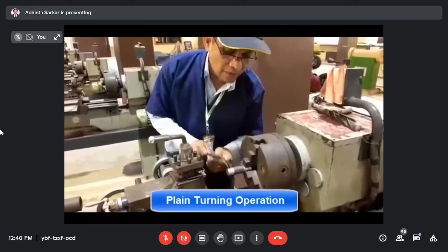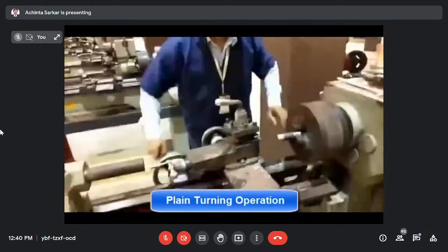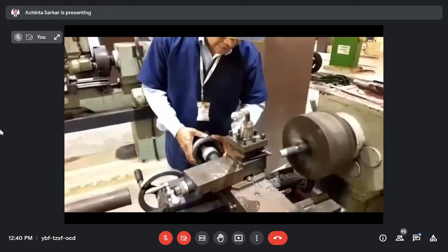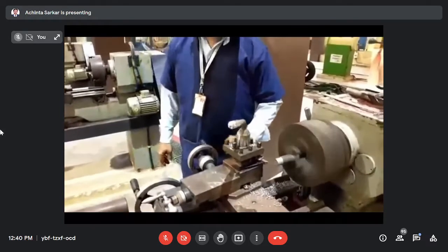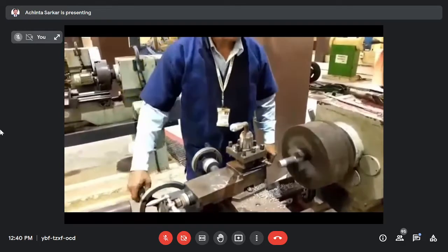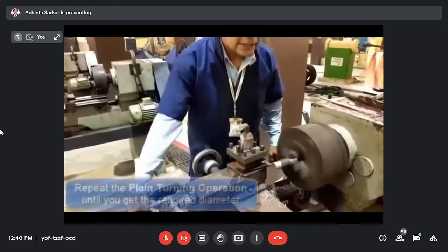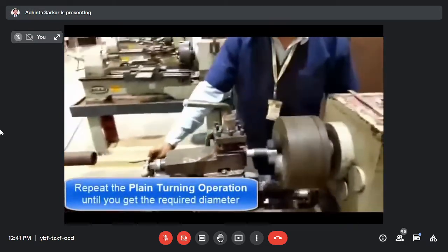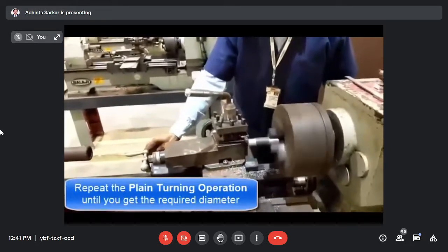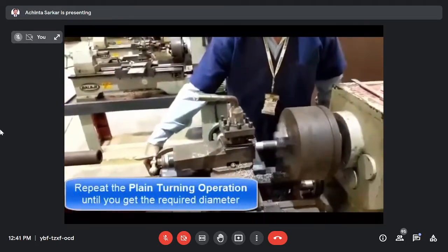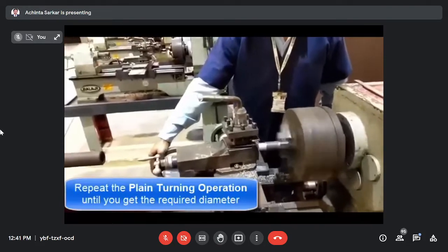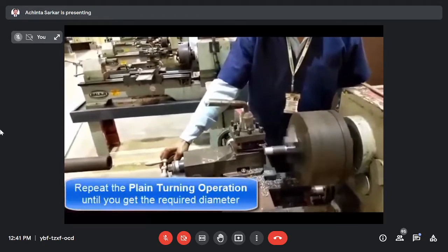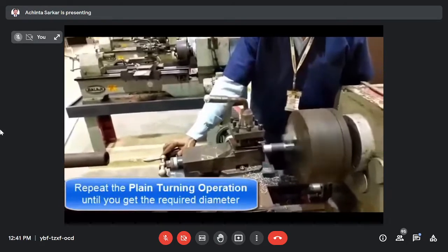No. 1 mm depth. Again here apply 10 divisions. 1 division is 0.02 distance. Then apply a fine cut to get the exact dimensions, slowly rotating the carriage wheel, and the feed rate is very less, and getting smoothness on the workpiece surface.